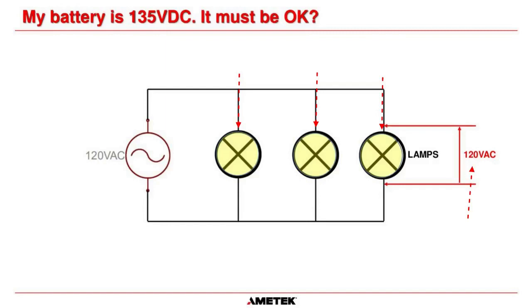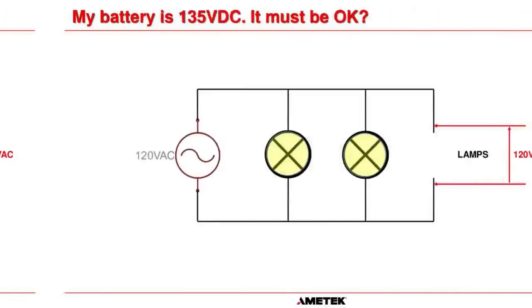if you measure across the power going into any of these lamps, you will measure 120 volts AC, because this point here is exactly the same as this point here, because they're in parallel. Okay? So hopefully you're following me on this.